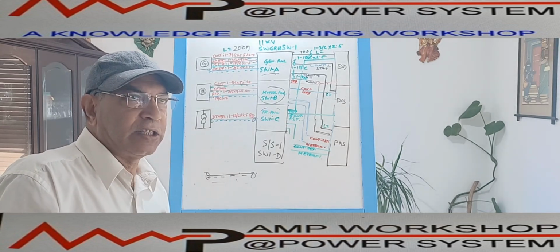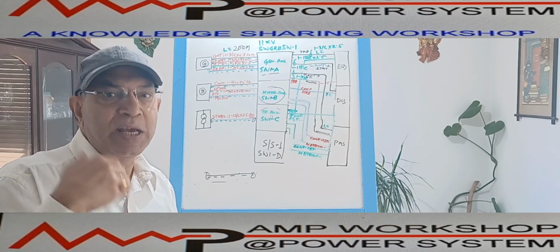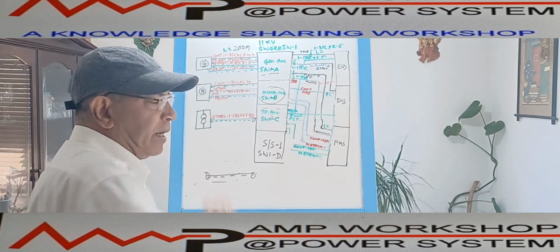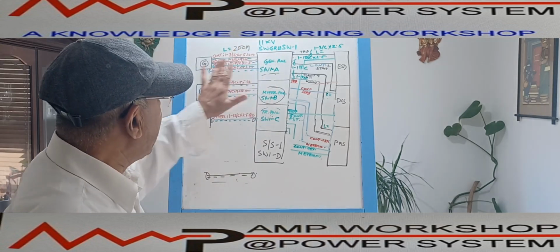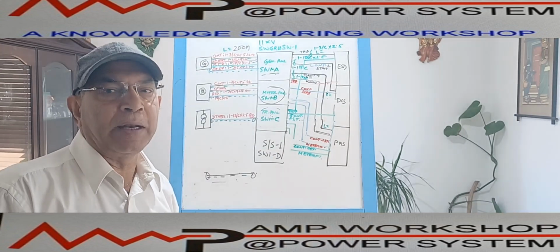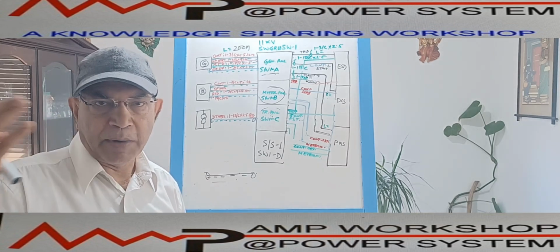The fire and gas system will give the tripping command or abnormal command through the ESD system. The trip command should also come to the generator panel to trip the breaker. So if we look at it that way, the generator panel, in addition to the generator, is also hooked up with other control panels and control devices, which are located in the control room or some other room.